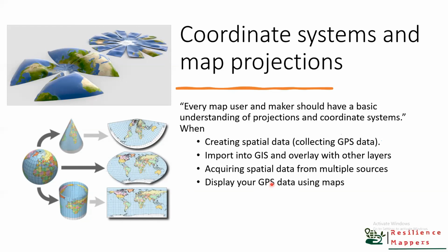When you're digitizing, it's also very important that you understand coordinate systems, because usually you have raster data in one coordinate system, and then the new vector layer that you're digitizing into is in a different coordinate system. That implies the data that you're creating from the digitization is going into a wrong area without you realizing it. But if you're very confident of your coordinate systems and projections, then everything will be good.